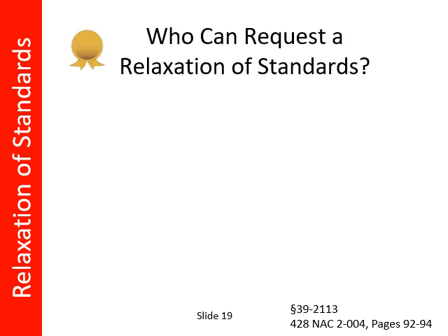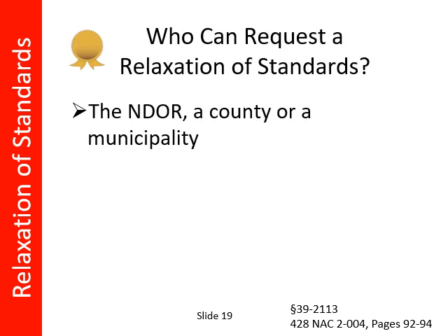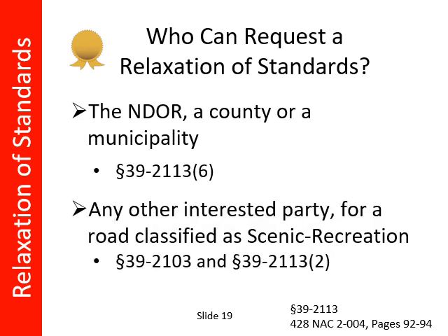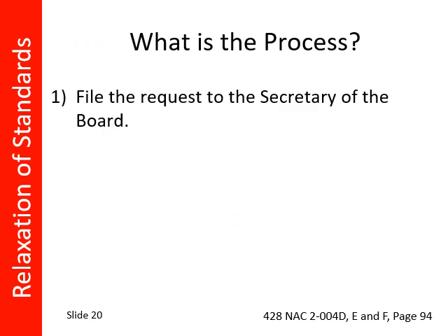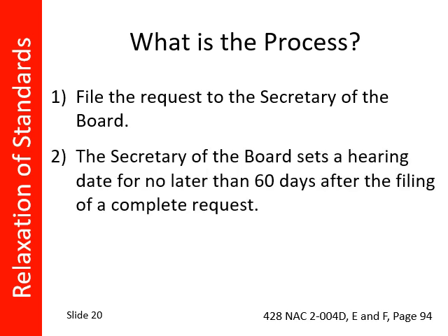A relaxation of standards can be requested by the Nebraska Department of Roads, a county, or a municipality, or for a road classified as scenic recreation by any other interested party if the party believes that the application of scenic recreation standards would defeat the purpose of the scenic recreation classification. Filing a request with the Secretary of the Board starts the process. The Secretary of the Board must set a hearing date for the request no later than 60 days after the filing of a request that is complete. The requirements of a complete submittal will be discussed later in this presentation.